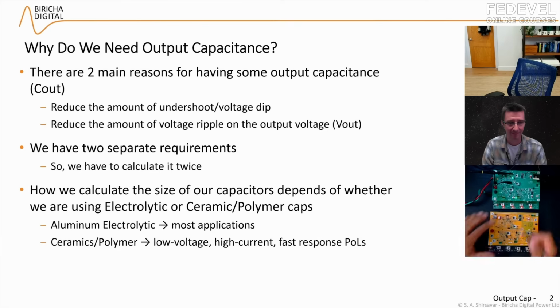Okay. So here I have a power supply. There are actually three buck converters here. The one that we're going to show is this one, and that is a synchronous buck. We will later talk about the constant on time in this chat. And underneath is the load. So these switches determine how much load I am giving to this power supply. This is exactly the type of setup that we use in our workshops, and the engineers who come to take the workshop get to play hands-on and experiment like I'm going to show you now.